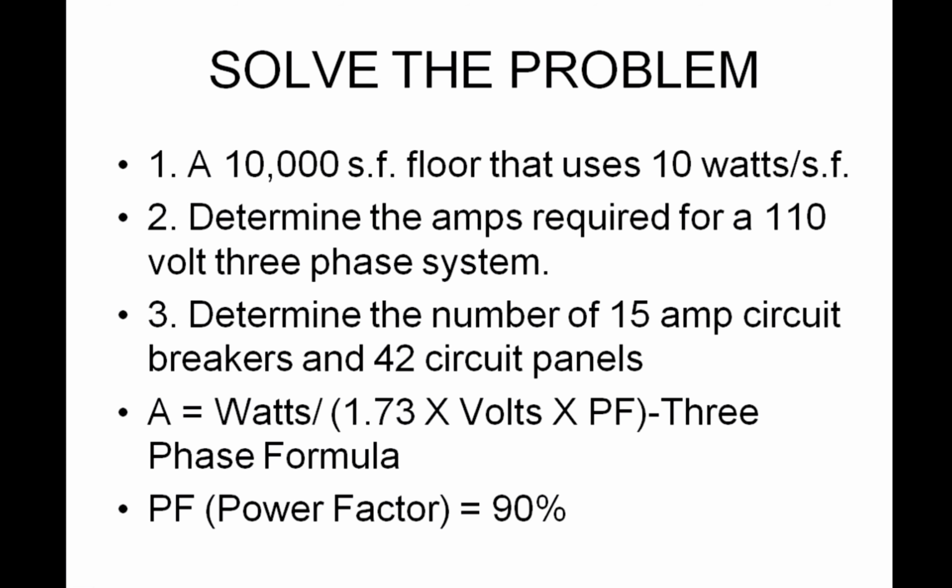You have a 110 volt three-phase system, which is typical here in the US, and you have available a couple of 42-circuit panel breaker boards that can accommodate, obviously, 42 15-amp circuit breakers. What we want to know from this problem is how many 42-circuit panel boards do you need?